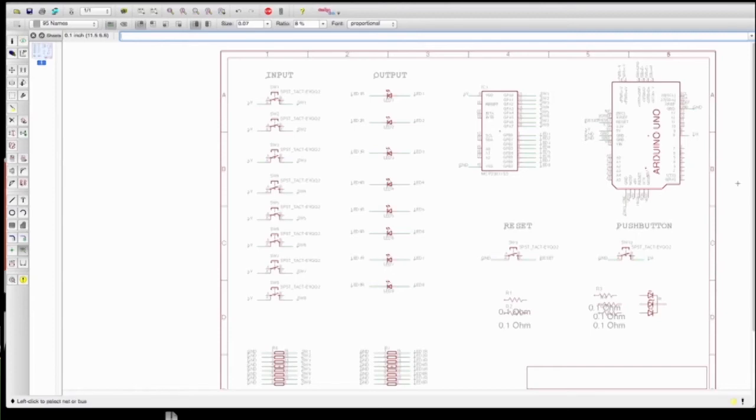And we're going to label these. We already have our buttons connected. This is just the labeling process. All right, and D8. All right, so what's left here? Let's go down, and we haven't connected the I2C stuff yet. So let's do that. We're going to create an I2C bus for SCL and SDA.